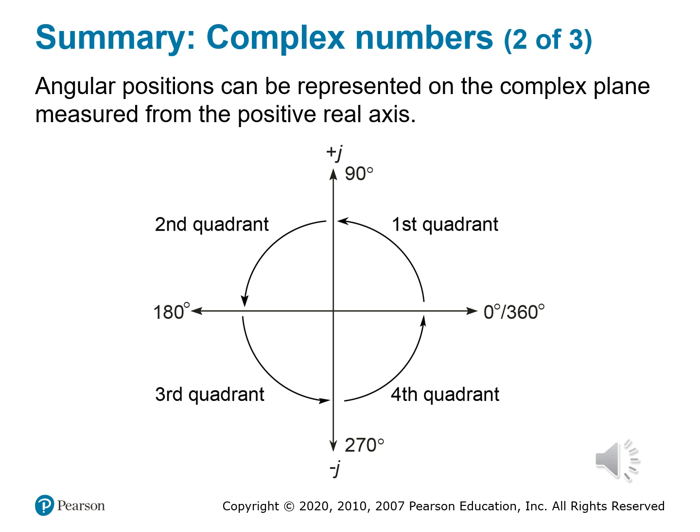Now, we travel it. On this complex plane, angular positions tell us where a phasor, our voltage or current vector, is pointing at any moment in time. So start off at 0 degrees along the positive real axis, move counterclockwise 90 degrees, that's straight up, into the positive j imaginary realm. Go further to 180 degrees, that's across the void, back along the negative real axis. Continuing to 270 degrees, down into the negative j shadows, and then coming back full circle to 360 degrees, back to where it all started.